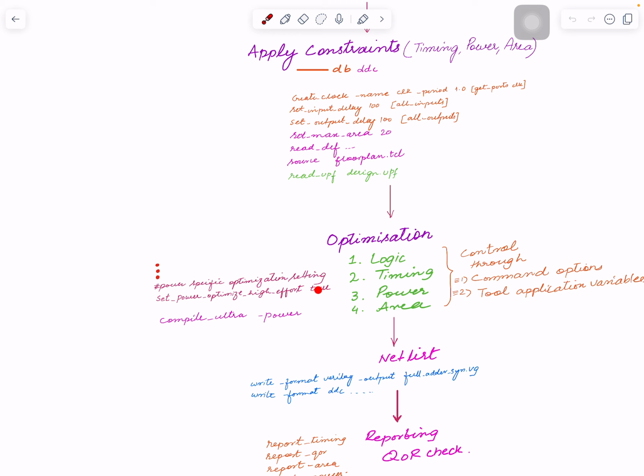It will optimize a lot of time, so your runtime, the time it takes for the tool to do the actual synthesis, will increase because now it's probably doing it inside a lot of iterations. That might have an impact on the timing because now you're focusing on high power. It's just sometimes not possible to optimize all timing, power, and area equally. You have to pick; the tool has to pick a priority somewhere. So maybe with this one, it will pick the power as a priority and at the cost of timing and